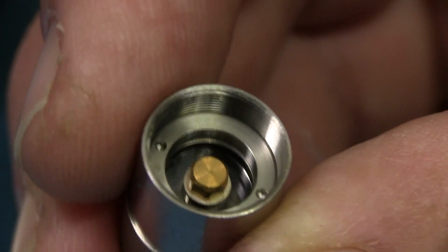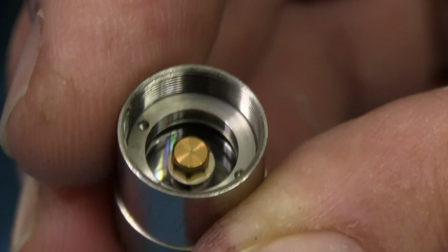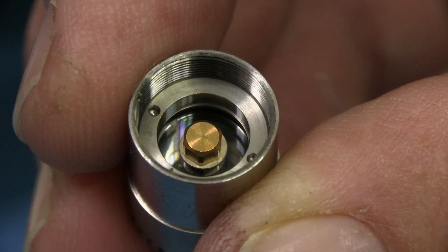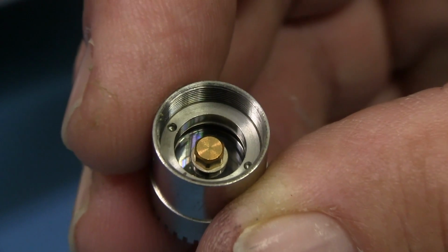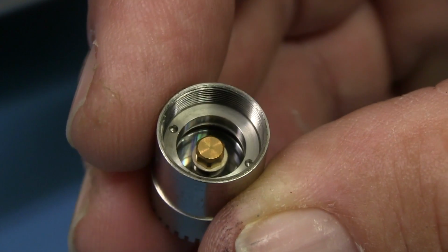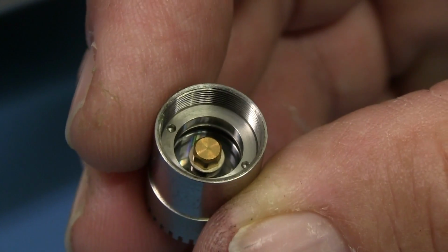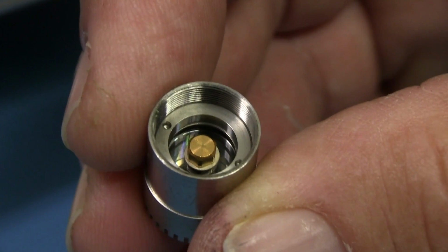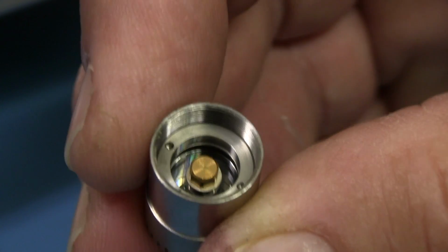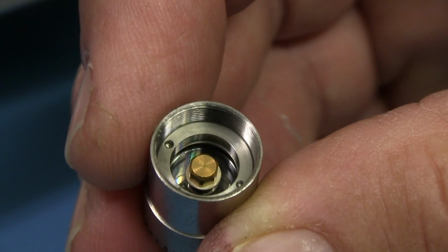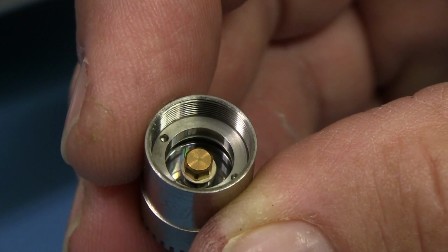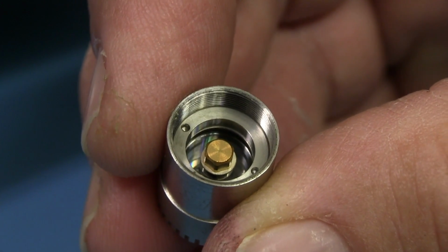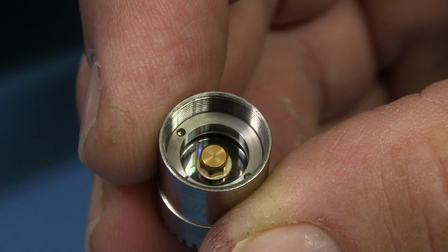Incidentally, these have got pretty much a rule of flat frequency response from about, I think, 10 or 20 hertz up to about 15 kilohertz. And from 15 kilohertz through to 40 kilohertz, the response is characterised. It's not perfectly flat, though. It deviates by about a dB and a half, something like that. That's still not too shabby. Yeah, it's pretty damn flat. So, in its main band, how flat are we talking? 0.1 dB, 0.2 dB, possibly flatter. In fact, I think that any deviations are more the result of the measurement system than the microphone.